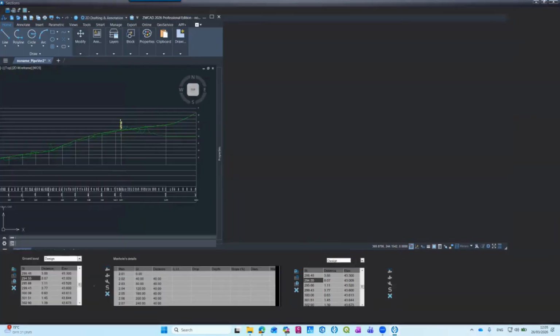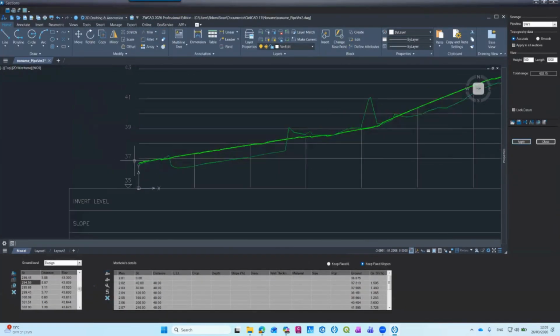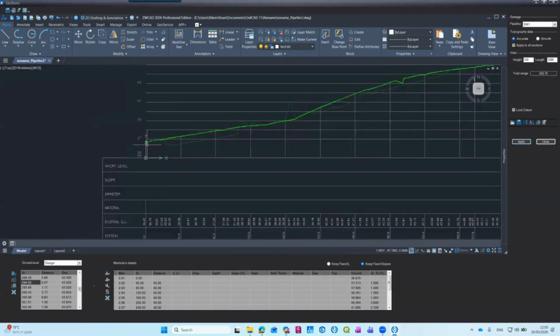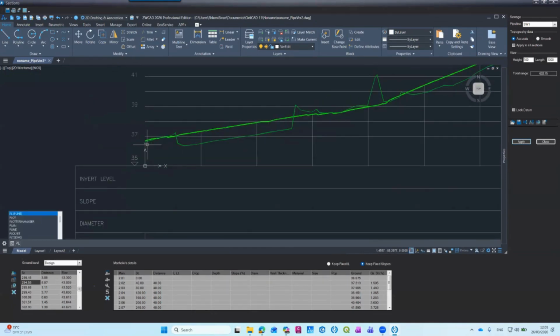Okay, now I want to continue, and I'm using the same methodology. You know what? This time around, I will just start with 1.5 meters in the ground, and I see the ground level is more or less 1.3%, and then goes up to here, and then goes 3.6%. So I will start with a slope of 1.4%. Let's see.